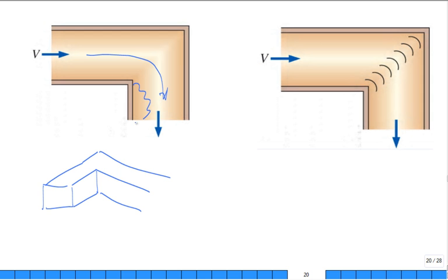You'll have a large separation region that'll have a large loss coefficient. Maybe the loss coefficient without any help is something like 1.1. If you put in some turning vanes, which are little metal inserts, you can buy them if you're in the HVAC industry and you want to help high performance duct systems. Every time the air is being pushed by the fan, they'll help navigate that turn. It'll drop that loss coefficient to 0.2. That's a pretty good reduction. But most of the homes don't have them.